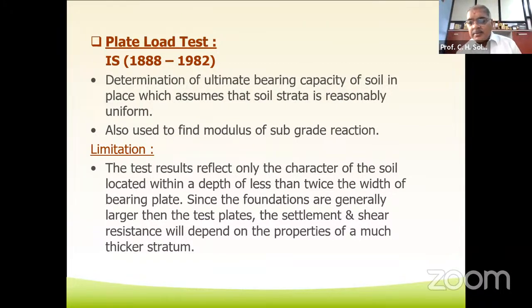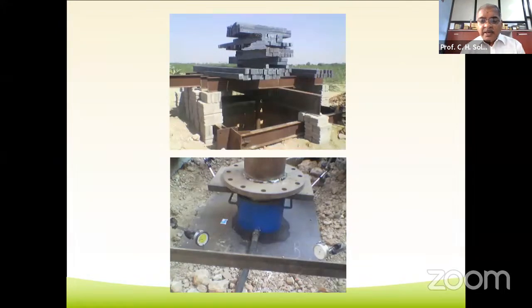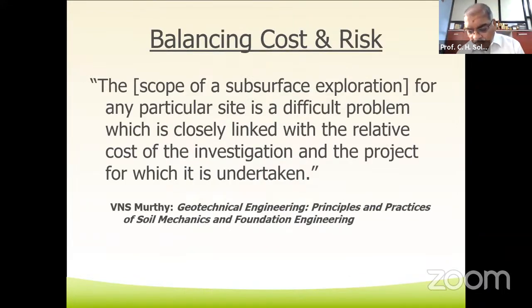As you know, the size of the bearing plate is about 1/5 of the width of the foundation. Since the foundations are generally larger than the test plates, the settlement and shear resistance will depend on the properties of a much thicker stratum. This is the arrangement of the plate load test.